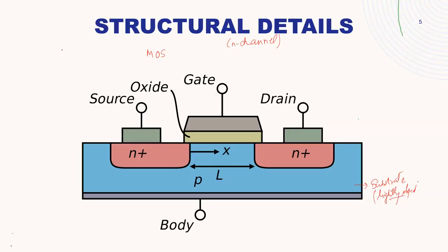Why is it lightly doped? This is your homework. I want to know why it is lightly doped and why it is not heavily doped, because you always see the source and drain written as N+. N+ means heavily doped. Got it? These are always heavily doped.